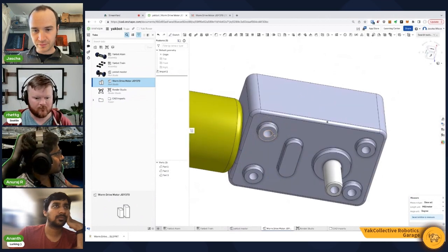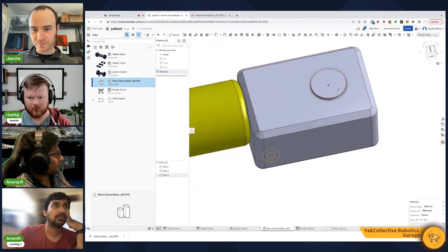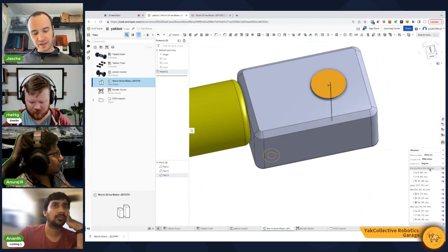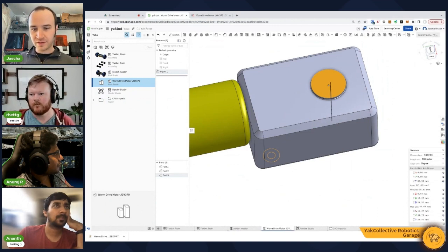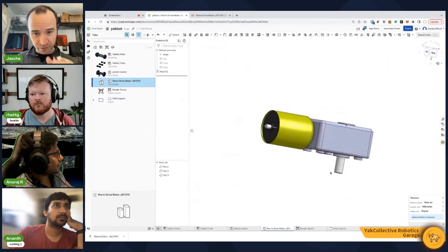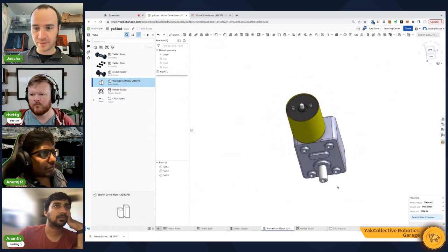So we need to know the bolt face to the furthest most extent. So the parallel distance is 24 and a half. See if I can also measure that. Yeah, checks out. Okay, so one thing that is different about this model from the motor I'm holding is it has the encoder on the back. Because again, the encoder is not always the option.